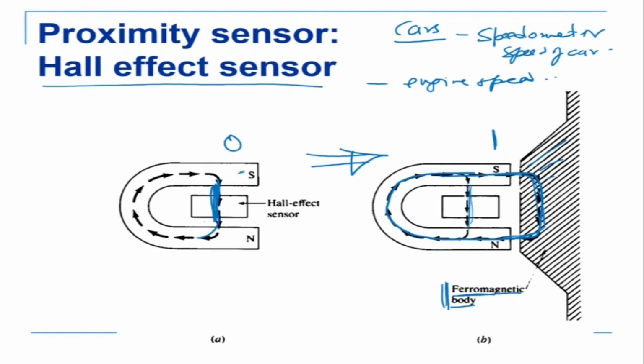So if you press the clutch and the car is not moving but the engine is running, then it will show you the engine speed. But if the clutch is engaged and the car is moving, then the speedometer will show you the speed of the vehicle in kilometers per hour. Okay, and how is that sensed? So that is essentially sensed by using a Hall effect sensor, and the Hall effect sensor is fitted onto the crank of the engine. Okay, and it senses the rotation of the crank. And number 2, so this gives you the engine speed. Okay, and it is also fitted on the gearbox.